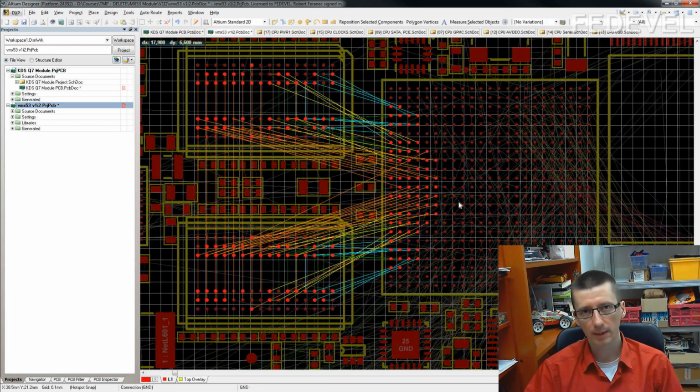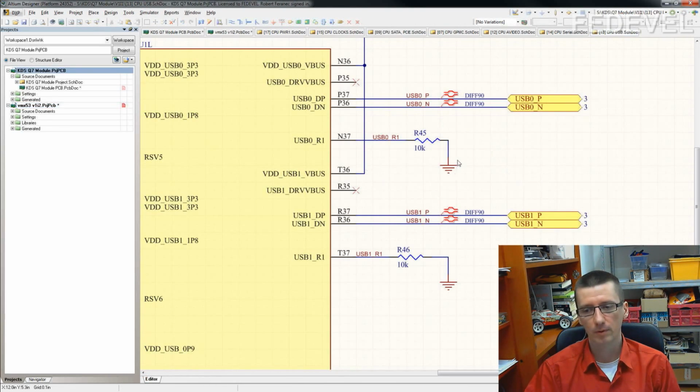Once all the decoupling capacitors are in place, I then do the second most important components, which are some kind of reference, precise resistors or capacitors, which are normally placed just between pin and ground, but they very often require a short connection and maybe a wider or low impedance connection.